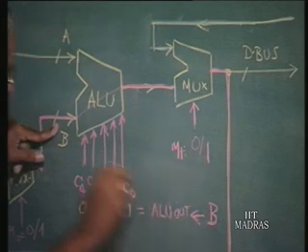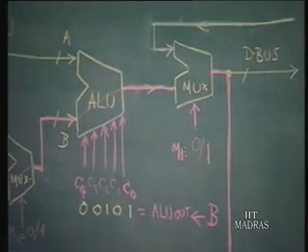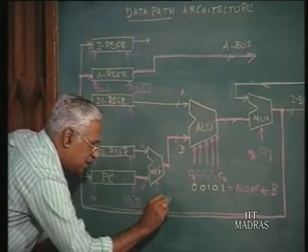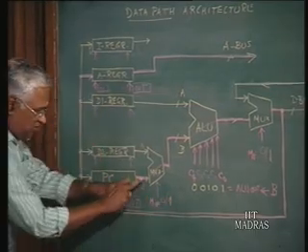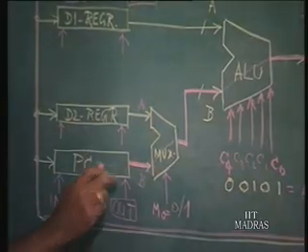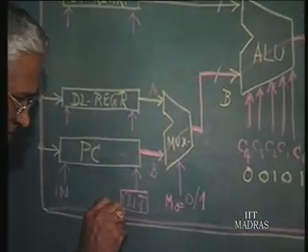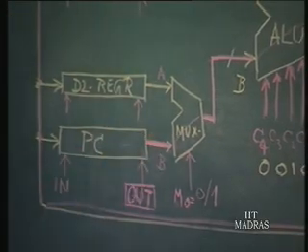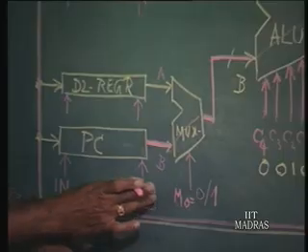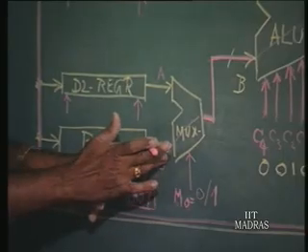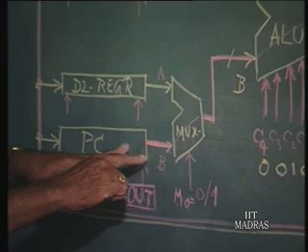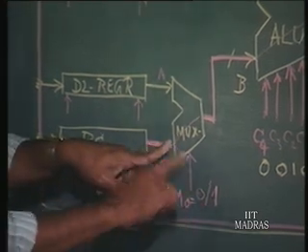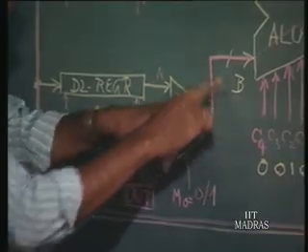Okay. So that we get this over here, and then this particular mux M0 again, let us say, is set to 1, so that this information goes there. To see that the PC contents are placed on the B leg of this mux, the output of the PC must be enabled, so the output is enabled so that it comes here, and this is 1 so that this comes and not the other one, and so on.